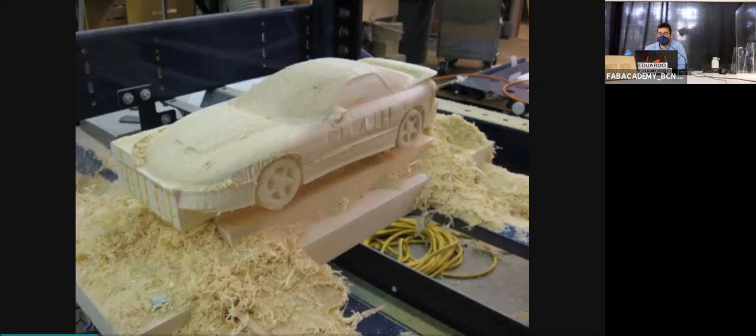So the basic shape of this car before was a block of foam. With a 3-axis machine, you can cut the top and more or less until half of it. You can only see the top projection of the car. You can only cut it. How do we cut the side? We use guides, and we don't have them here, but we can use these guides and a rig to rotate our foam and produce the other side of the cut. And then when we have finished the top and the side, we can rotate in the other direction and produce the other cut of the side. So we have a quite annoying process with a lot of manual labor.